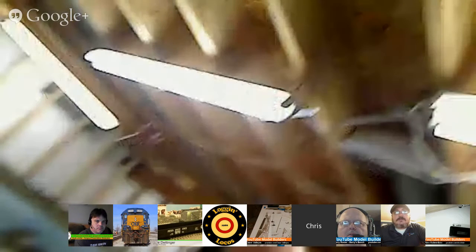They have a board that's a little bit more money than the quad controller. It's called Quad LN, which has a Loconet jack, so it can report turnout status back to JMRI over Loconet. So when I do my layout, I'm probably going to use the Quad LNs, even though it's a little more money than the quad turnout board. But I think it'd be better to have the feedback, because otherwise you have to have feedback through some kind of signal system to tell you the status of your turnout.